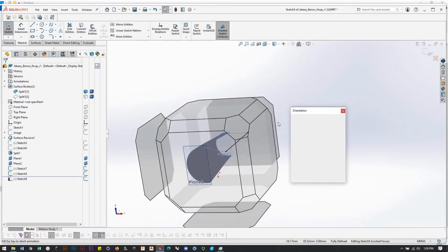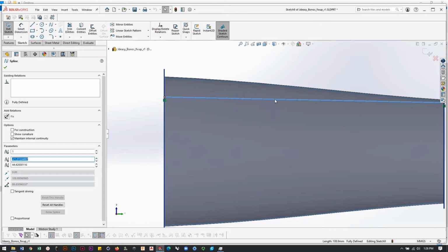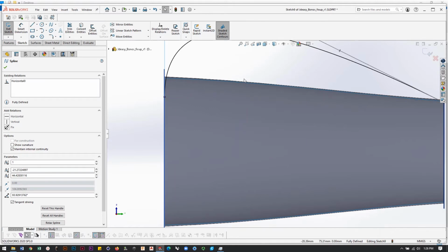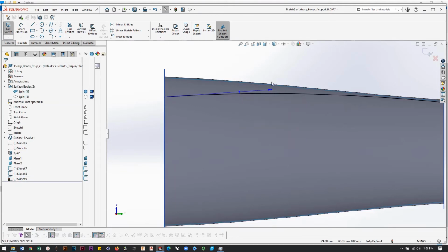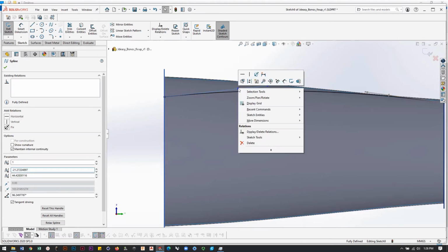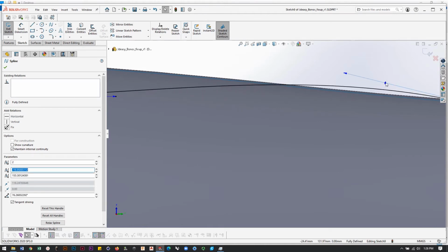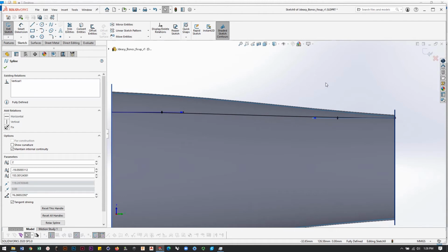I'm going to look at this from the side view here. Nope, we're going to set a vertical constraint on the side view sketch here, not horizontal. And I'm really finding with SolidWorks 2020, you really need to bend the arc. You need to bend the handle of the curve to get the opportunity to add a condition to that handle.